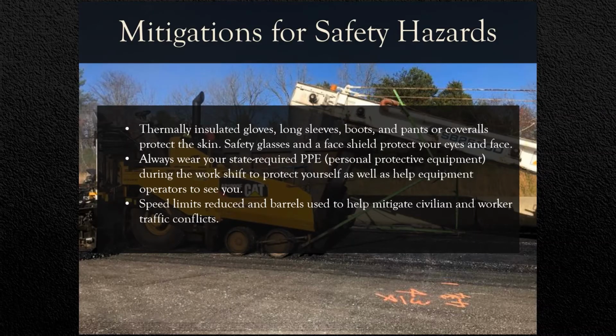Thermally insulated gloves, long sleeves, boots, and pants or coveralls protect the skin. Safety glasses and a face shield protect your eyes and face. Always wear your state-required PPE during the work shift to protect yourself as well as help equipment operators to see you. Speed limits are reduced and barrels should be used on the job site to help mitigate civilian and worker traffic conflicts.